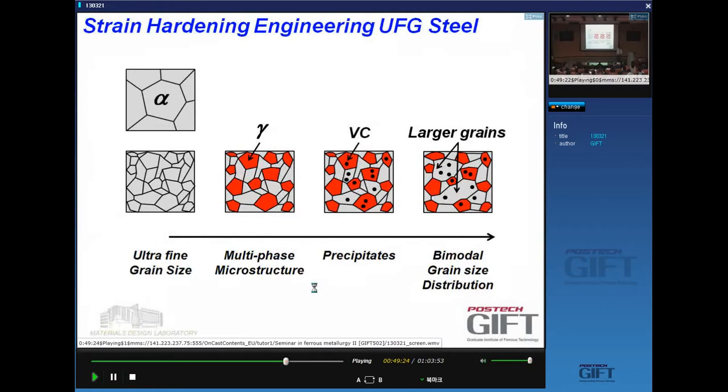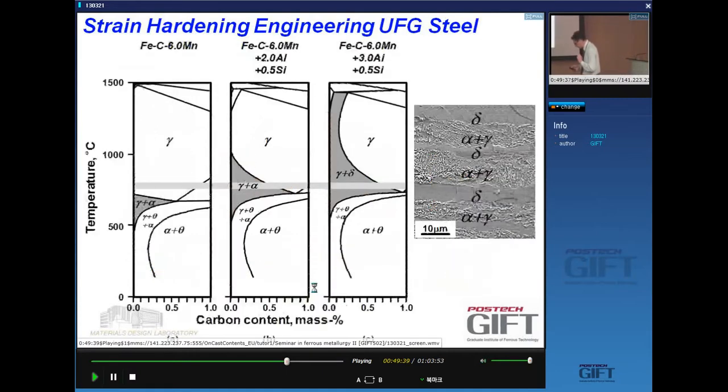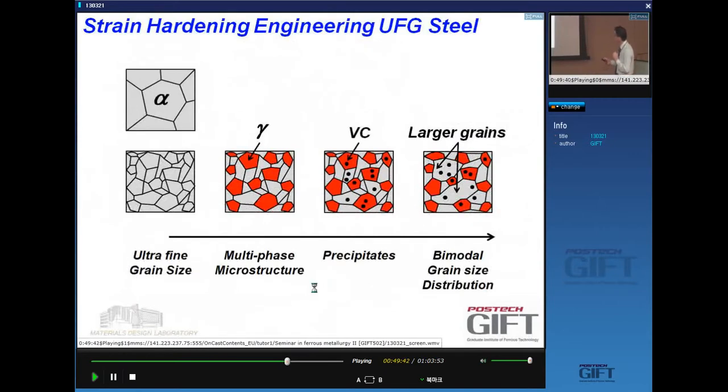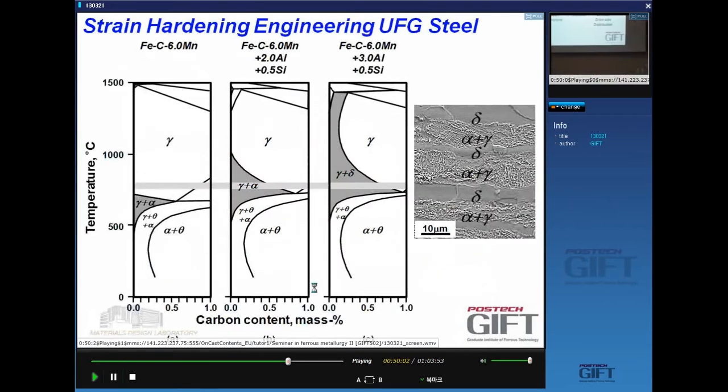And there, again, came this idea from Dr. So that if you add some aluminum to the compositions, you can change the microstructure. And instead of having a microstructure, yes, where both the ferrite and the austenite are ultra fine grain, you have in addition, yes, some larger grain, yes, and so what you have to do for this is adding aluminum.